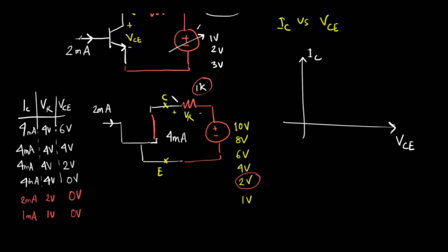So if the transistor voltage has to remain at 0 volt, then the transistor current must change. Alright, and this current is now determined by, well, using KVL in this loop. Okay, this current is no longer controlled by the input current. This is controlled by the output loop. This is actually the saturation condition. Okay, so if we plot IC and VCE, what can we see?